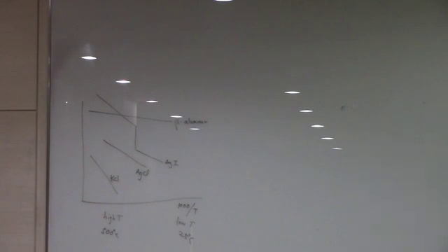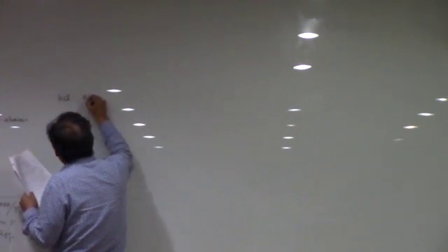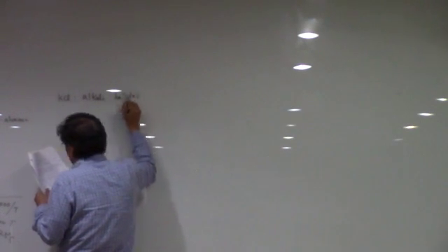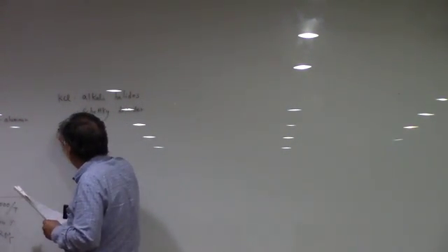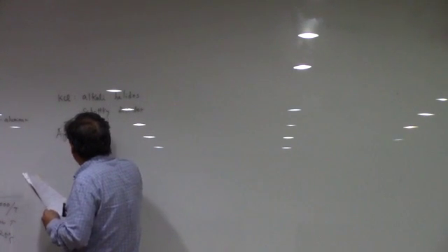So you can see the beta alumina shows relatively high ionic conductivity over the whole temperature range. Here, the KCl is an alkali halide and a Schottky disorder material. And AgCl, which shows higher conductivity than the KCl, is a Frenkel disorder material.